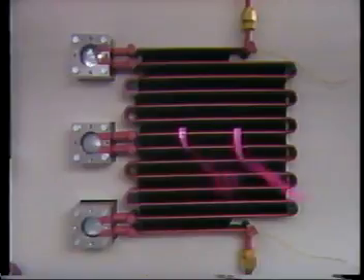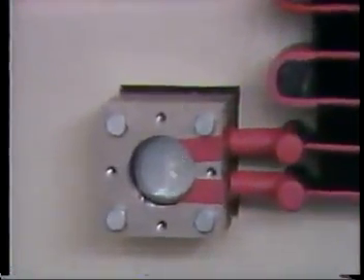We will now see how the refrigerant changes its form from gas to liquid. The refrigerant being sent to the condenser is still very hot and generally looks like a mist. In other words, it is usually a gas when it reaches the condenser. As it flows through the condenser for some time, the majority of the refrigerant becomes a liquid containing some gas bubbles.